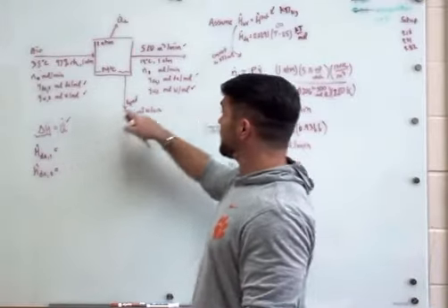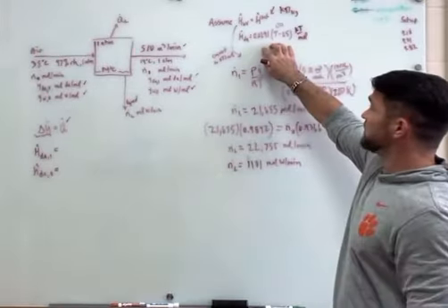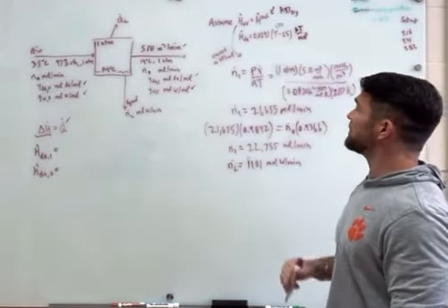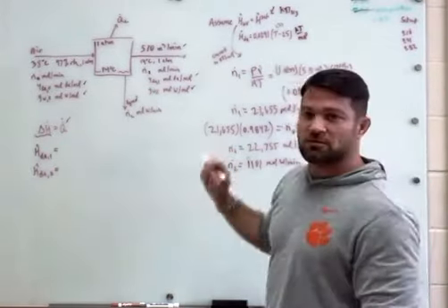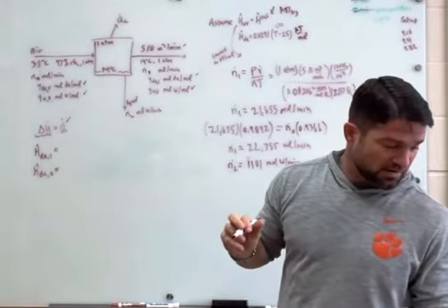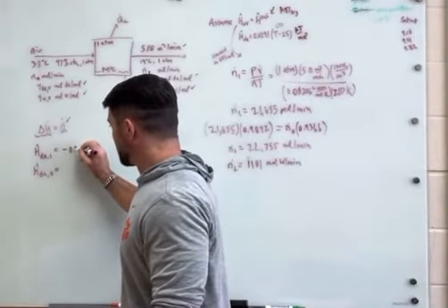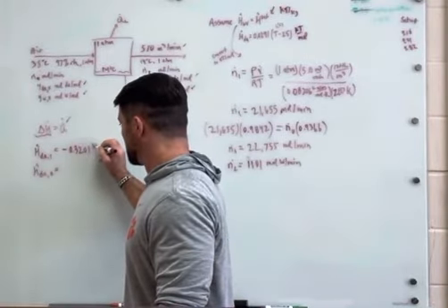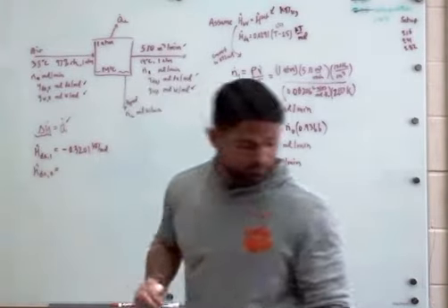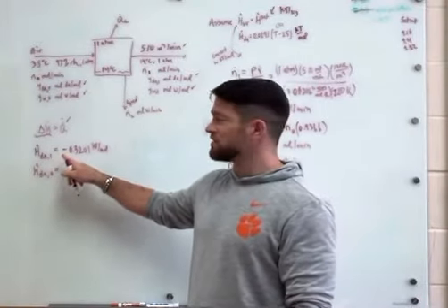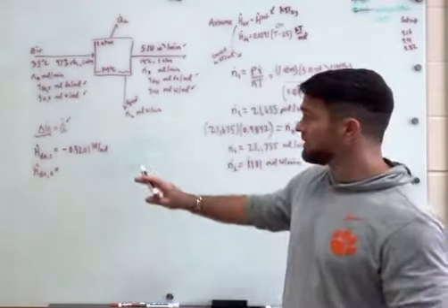To get that of the dry air coming out, I just use this relationship right here: 0.0291 times T minus 25, and the temperature of this stream is 14 degrees C. If I do that, I get negative 0.3201 kilojoules per mole. This is a negative value, which is okay. We'll come back to that in a second.